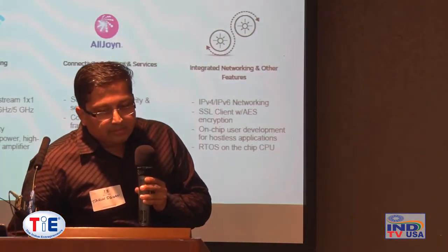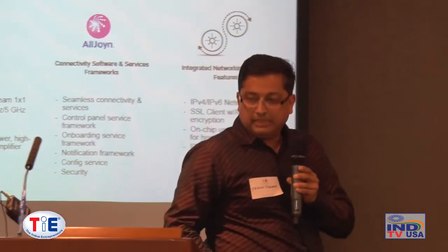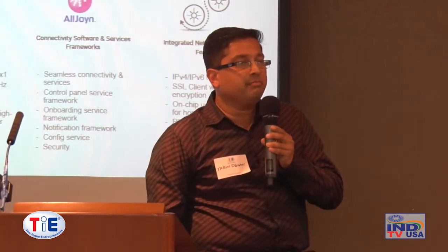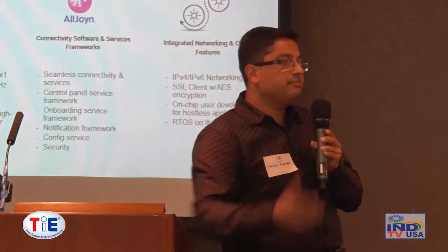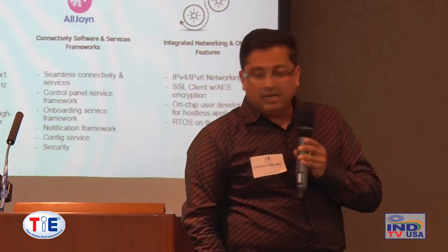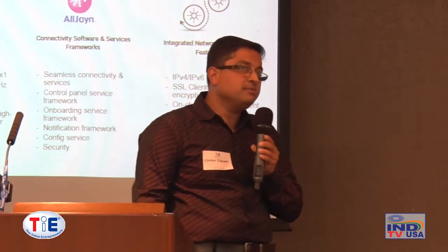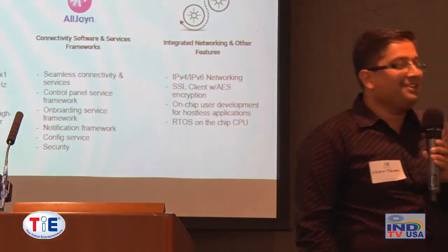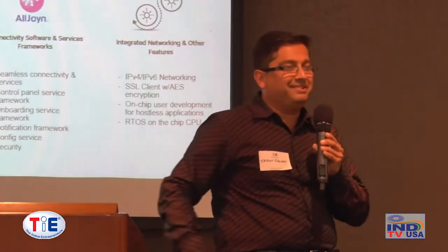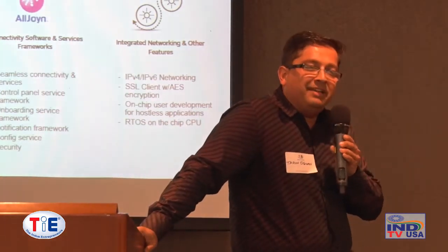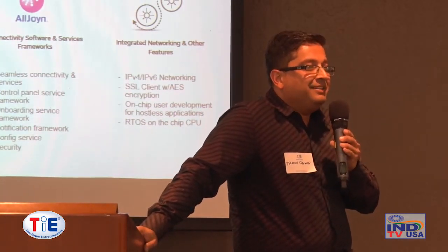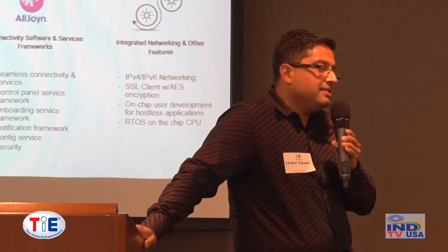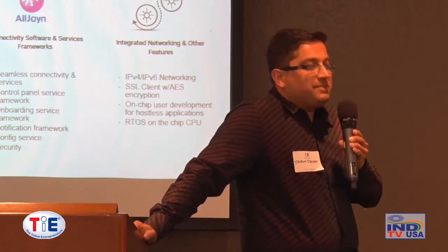Okay, so this is a specific product that we worked on at Qualcomm. It has a product name, which I won't get into, but what we have focused on is power management. So I'm giving you a product perspective on the SoC now. Let me explain what I mean by power management. It's actually a very simple concept for these kinds of devices. Most of the time, these devices are sleeping and playing dead, and you want them to be playing dead most of the time. That's really what power management comes down to. And how much intelligence can you gather in the device while it's sleeping? What are the different sleep states?